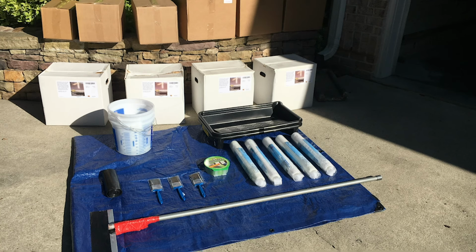That's a really good point. In the technical data sheet of any product, any reputable product, any product I've seen is going to give an acceptable application range in terms of temperature, humidity. They'll probably direct you to check the dew point before application, because we're dealing with a product that is going to chemically react. It's going to chemically react either by heat, by humidity, or a combination of both. But these are products that require their environment to influence how they behave once they're combined. They're reactive materials. The most important thing I would think, besides reading the technical data sheet, which is going to give all the readings at a fixed temperature.